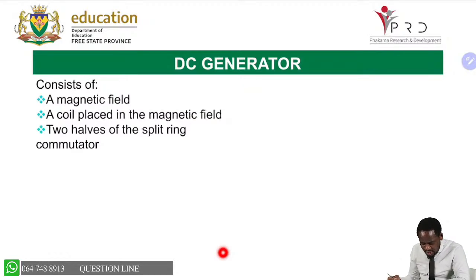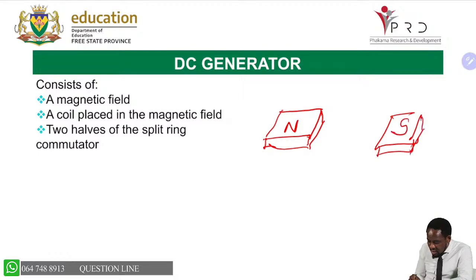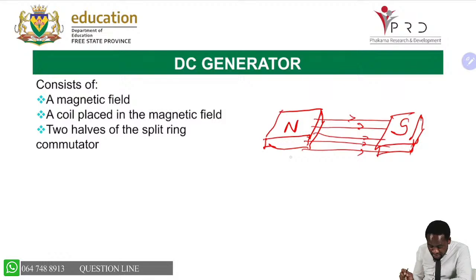We know that a DC generator consists of a magnetic field, which is a result of what we refer to as those two pairs of magnets. Suppose that's our north pole, and that's our south pole, something of this sort. What exists here is an invisible magnetic field. Hence we say it consists of a permanent magnetic field as a result of the magnet. If we place a coil in a magnetic field, and the two halves of the split commutator, it will give us the direct current that we are referring to.